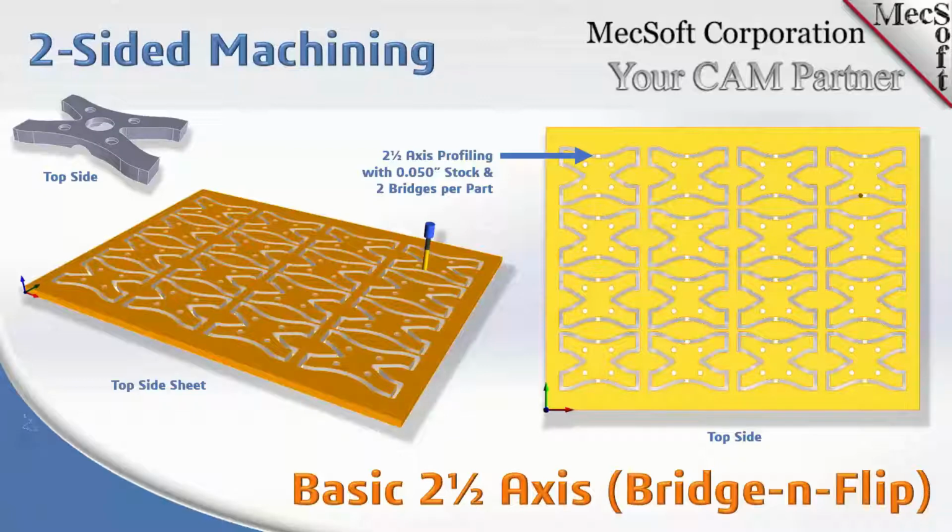So basically, the important thing to remember in each of these types of flip machining is that the part and the stock are aligned in the center, in the X and Y, and in the Z. Obviously, in a sheet machining like this, your thickness of the stock is most likely going to be the same thickness of your part, so it will automatically be aligned in the Z-axis.